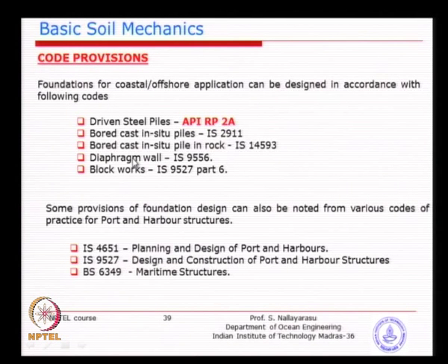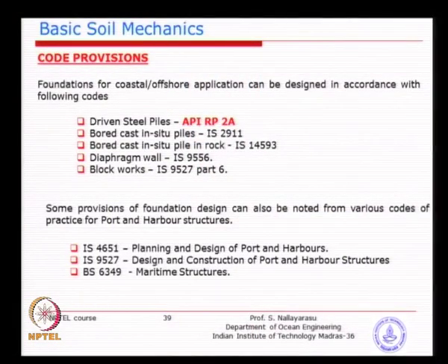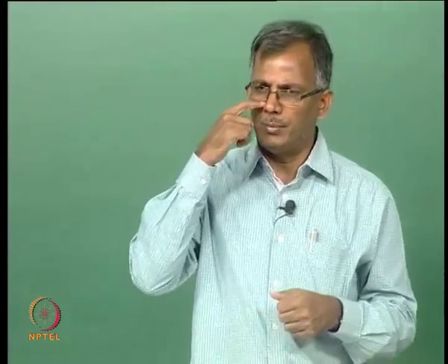Diaphragm walls, I think I have shown you some picture in the previous session. The diaphragm wall is nothing but a retaining wall, only difference is one side is water, the other side is soil. Very often used in port and harbor structures, which is just creating an interface between land and water, so that the ships can come closer. Diaphragm walls are also used in onshore construction nowadays. You might have seen some of the high rise buildings, especially when they have a basement of 2 or 3 levels of car park, you actually create a diaphragm wall very similar to a retaining wall.